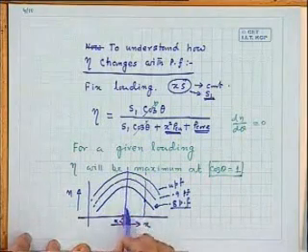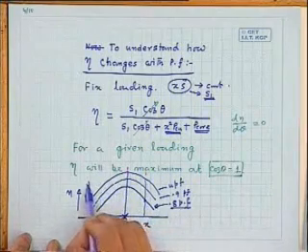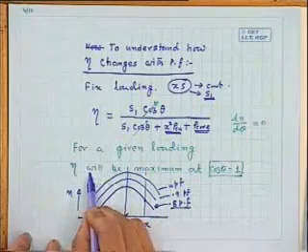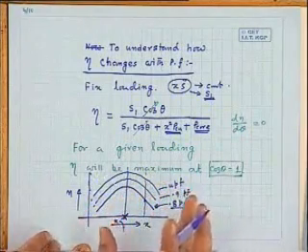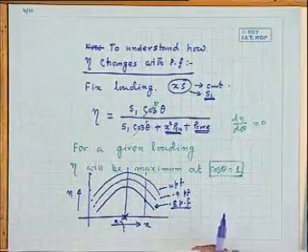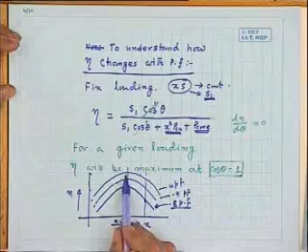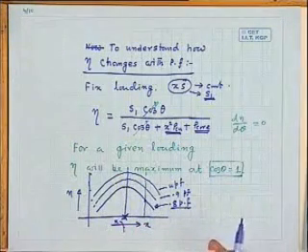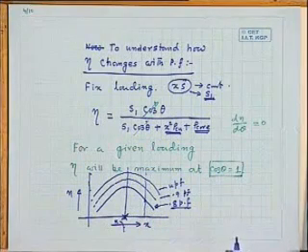Now, if it is 0.8 power factor, efficiency maximum, you can have this one. So the highest one can obtain at unity power factor. Therefore, let the transformer be operated at unity power factor such that the maximum possible efficiency can be derived from the transformer.